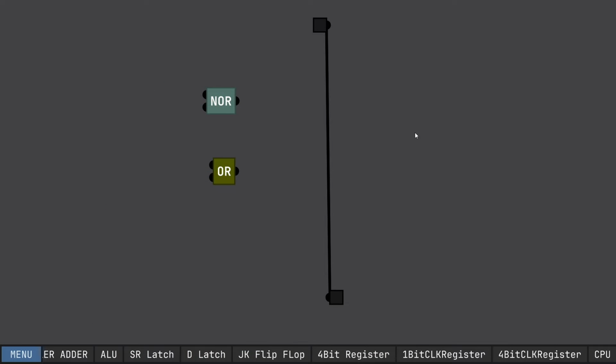But first of all, I want to get into a very core concept of a bus. So we know it's a common electrical point for gates or components to spit data out. So let's say we have this OR gate, and it's spitting out a 0 onto the bus right now. But if this NOR gate also connects to the bus, it's spitting out a 1. So the bus doesn't know whether it needs to be 0 or 1, and the simulation represents this as a flash.